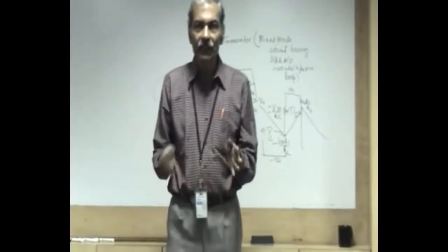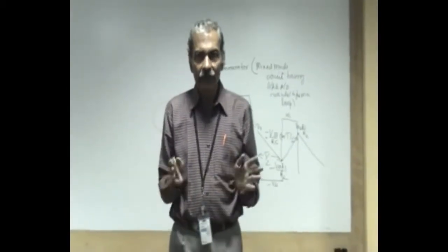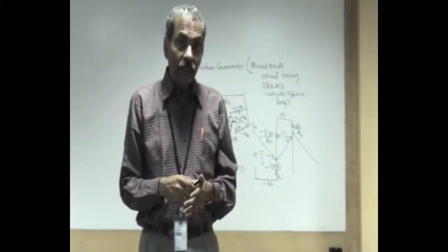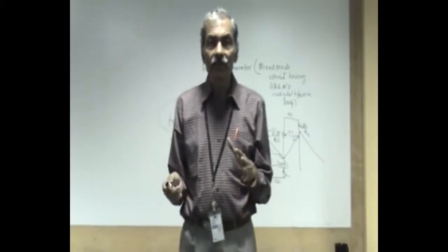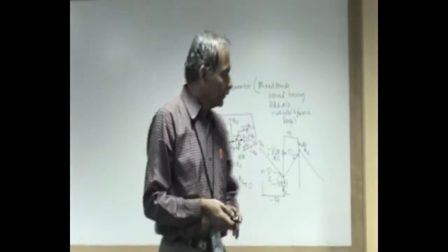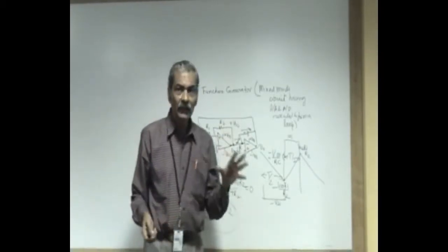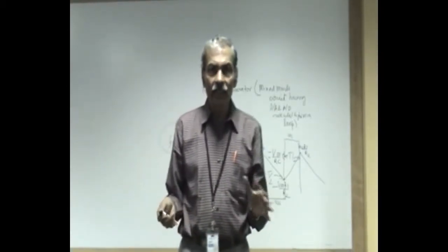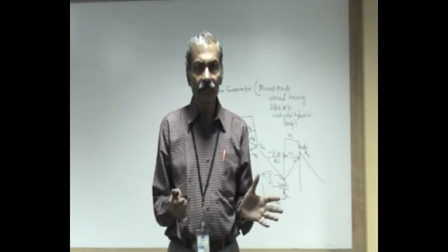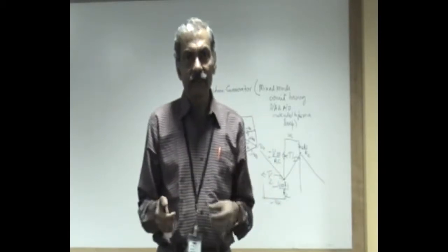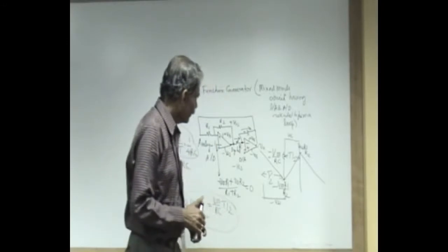So this becomes a highly stabilized amplitude square wave and triangular wave, and this triangle can be converted by using a diode function generator into a precise sine wave of required distortion, or you can make it go through a saturating amplifier just to get about a 3 to 4% distortion sine wave. So that is the function generator. It has replaced all RC oscillator and test oscillator circuits, which earlier used the Wien bridge oscillator, with this kind of chip, which is very cheap, for laboratory purposes of generating waveforms.